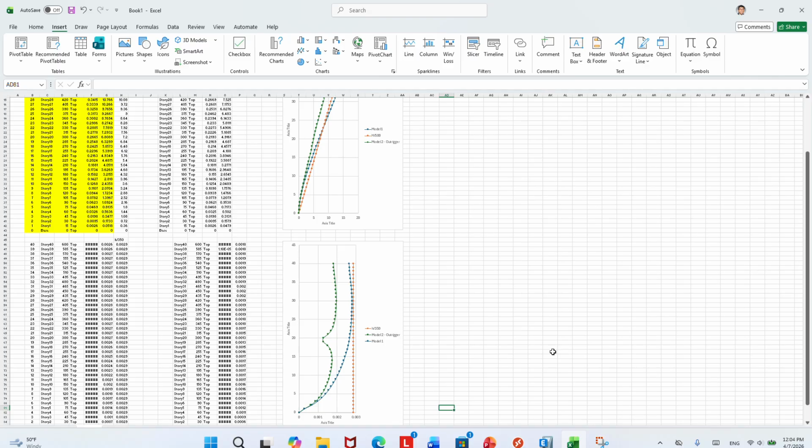One is overall drift. See that difference, right? This is basically because we increase the stiffness, the cantilever stiffness. So you see that overall drift comparison. Now this one is interstory drift ratio between two adjacent floors. So this is our criteria. Whatever, just two floors' interstory drift, right?